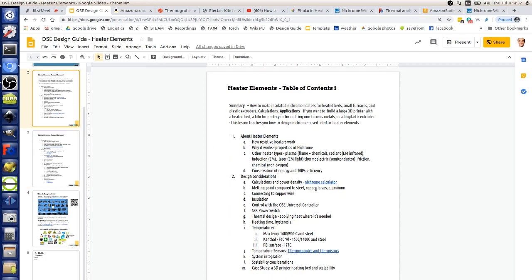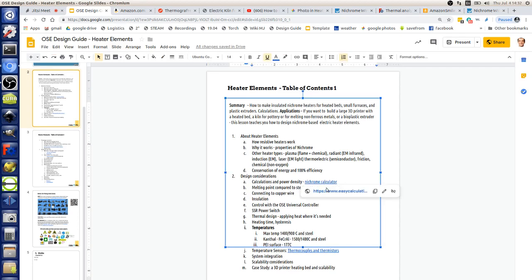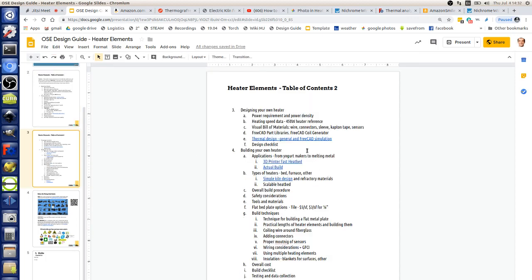Did you do wire pulling? Yeah. Easy to feed wire, insulated 14 gauge or something through. Tape that with electric tape to your nichrome and pull all that through. We tried that, but what happened with the sleeving was that the sleeve is so loose that things just very readily tend to go right through it, and then it all taped up. That's what we did, and at that point we fed it relatively effectively, but I think the finding from there is that it's not super practical because of the difficulty, unless you really refine it and have like the pulling wire thing.